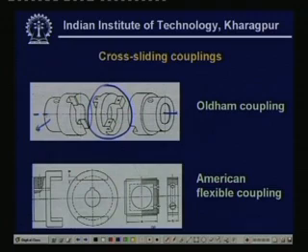Now you see, here we have a revolute pair. In this location we have a prismatic pair, and there we have another prismatic pair, and again this is a revolute pair. You might have learned that the kinematic inversions of these mechanisms may be the elliptic trammel or hand operated pump, etc. Now, the Oldham coupling, how does it operate?